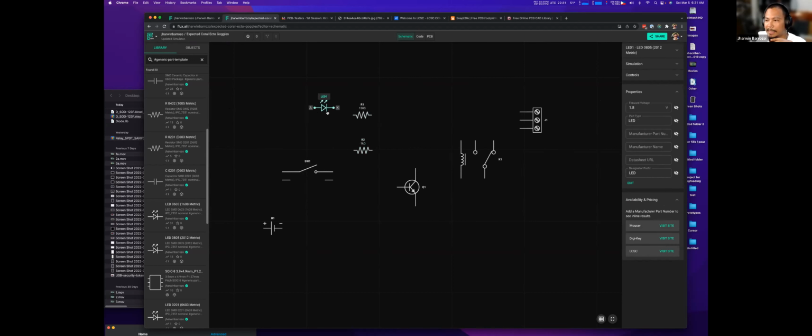As soon as I paste the part number here, the availability and pricing will kick in and give me the part availability. So this particular resistor that I just put the manufacturer part number for is available in LCSC. It is 8,550 in stock, and that was updated just an hour ago.